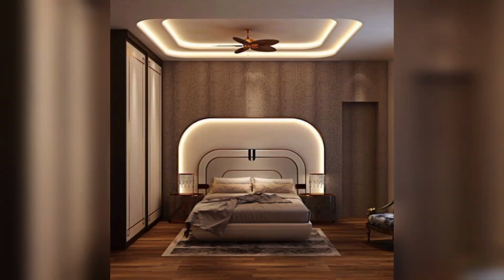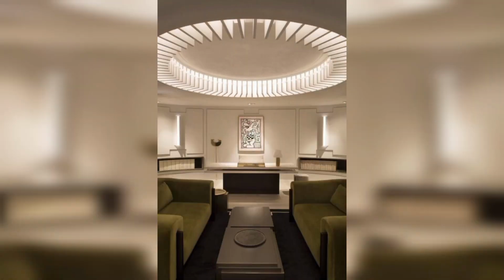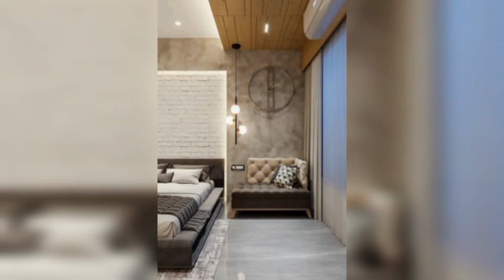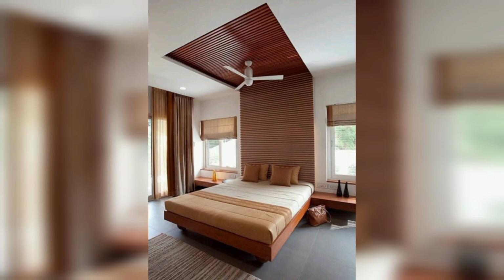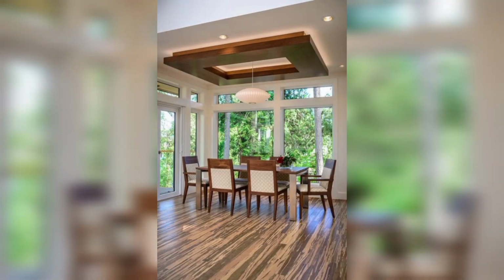So the most common type of ceiling is the dropped ceiling, which is suspended from structural elements above. Panels of drywall are fastened either directly to the ceiling joists or to one or a few layers of moisture-proof plywood, which are then attached to the joists.